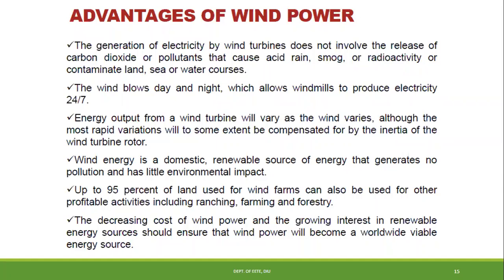It can work, but why is the wind vane used? Suppose we all know that the wind always tries to flow from the south direction. So we placed the whole wind turbine towards the south. Now suppose the wind direction changes and it is flowing from the east. At that time, the blade of the wind turbine is not getting the force from the wind, because the direction it should be has now changed. So for that reason, the whole wind turbine should be rotated to the east. At that time it will get the force from the wind.